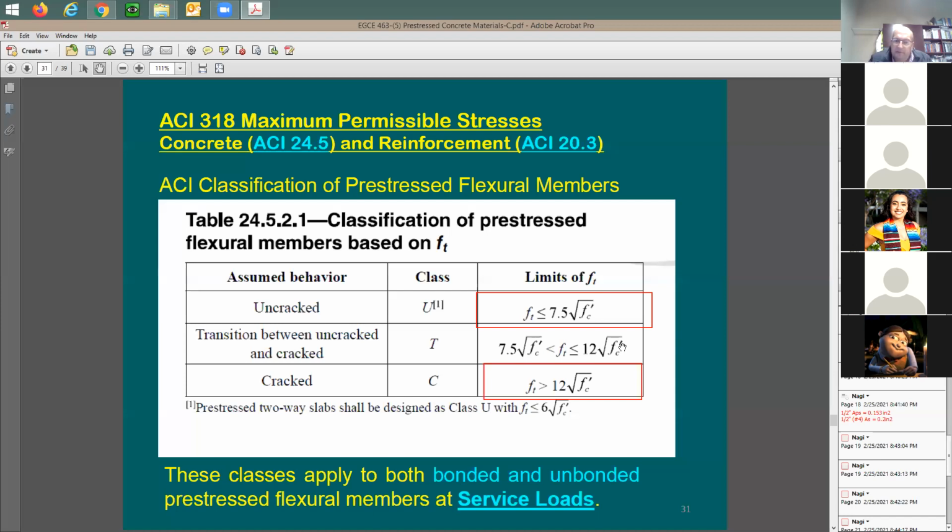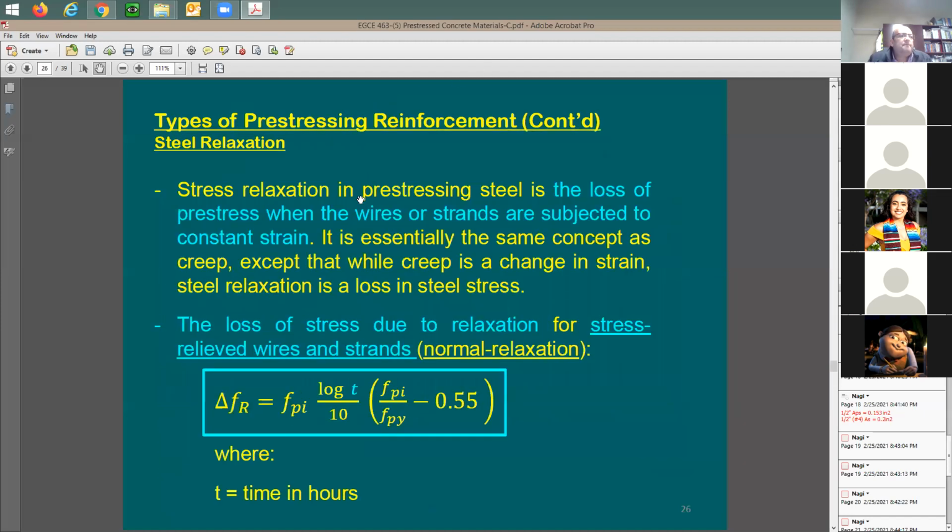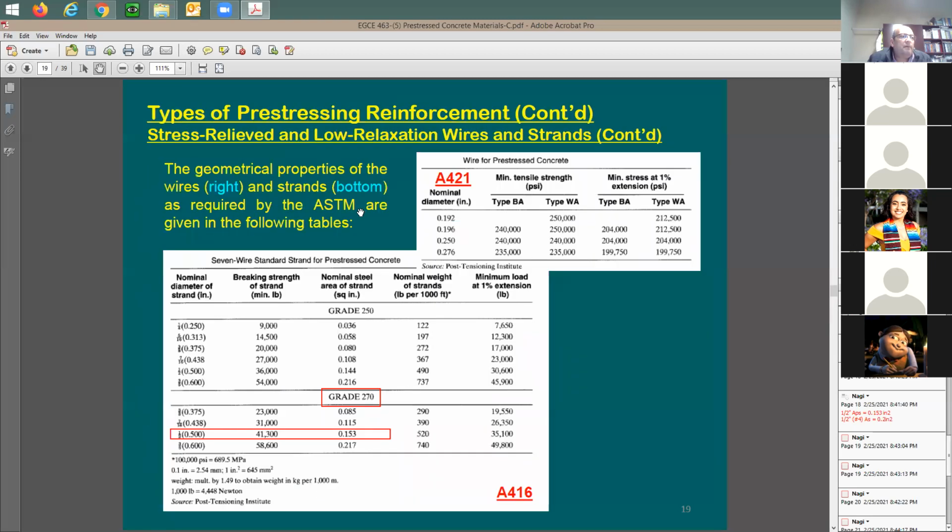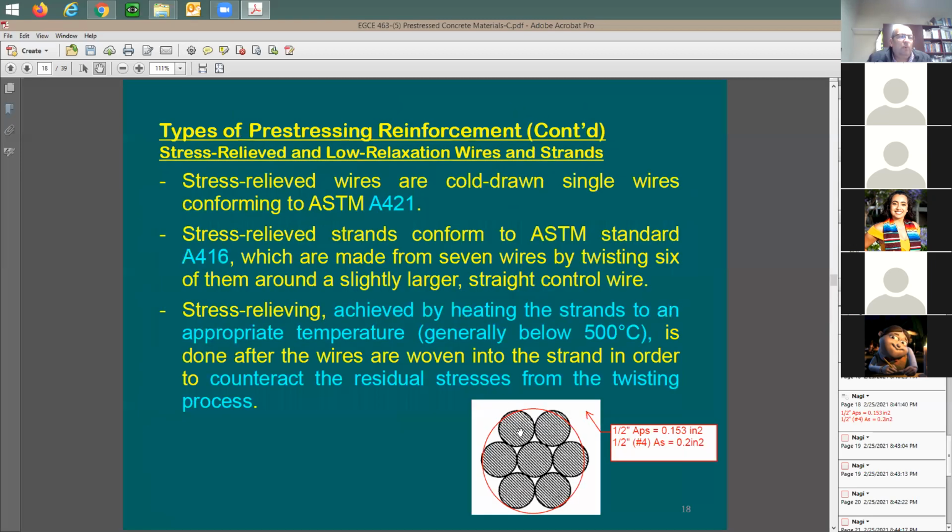But not also the same kind of material, like they dip the rebar, like the coated rebar, that green stuff. Oh, you mean the epoxy coated? No, they don't do epoxy coating, because just think about it. How would you do epoxy coating on this strand? Good point. Once you start to put them all together and twist them, you're going to be breaking all the epoxy. So if you coat them before you twist, you're going to be chipping off all the epoxy coating, right? You cannot keep it.